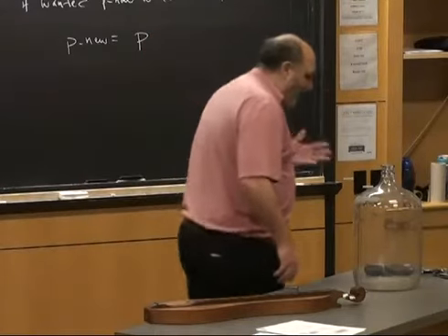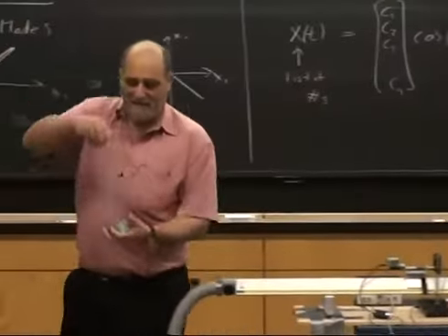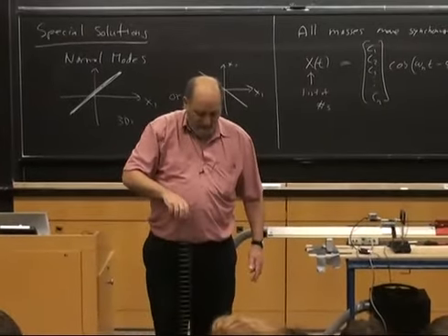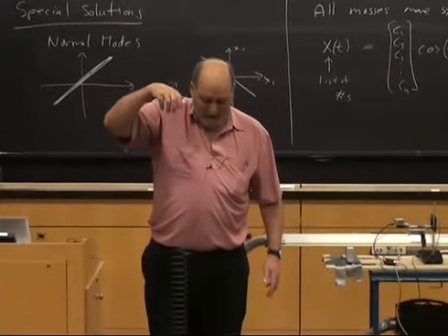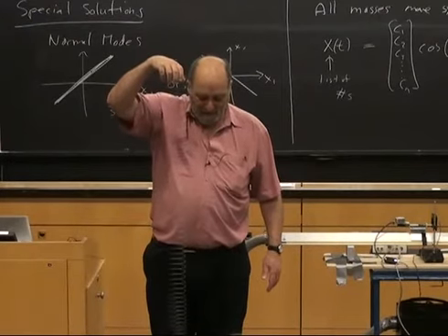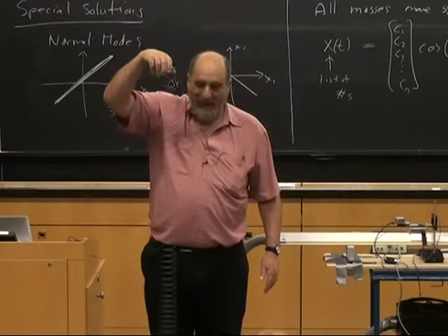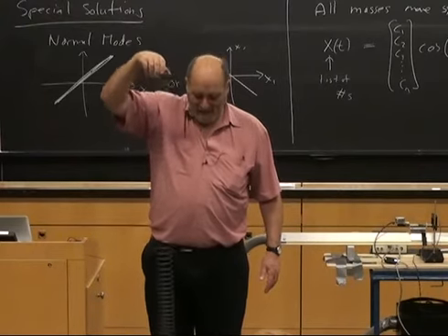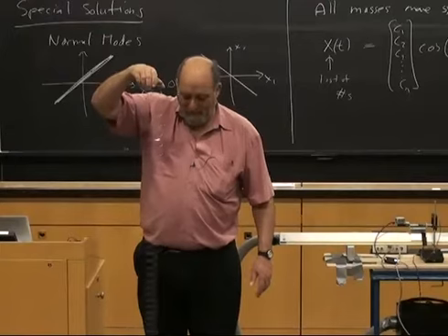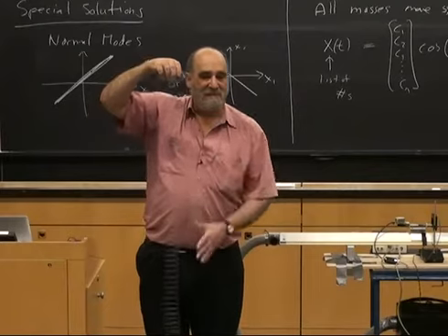Now normal mode vibrations are all over the place. Here's another elastic system. It's a weird elastic system. Relative to an equilibrium position, I can write linear equations for this. And this has a normal mode solution. The lowest mode, the slowest one, is about like this. Now if I try to get a higher mode of this one, I can't, it's hard to find it, and I haven't found it successfully by shaking, but it has a whole sequence of modes. All of these complicated motions that you see are somehow a superposition of those simple modal solutions.